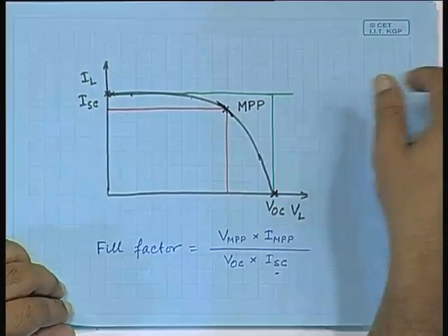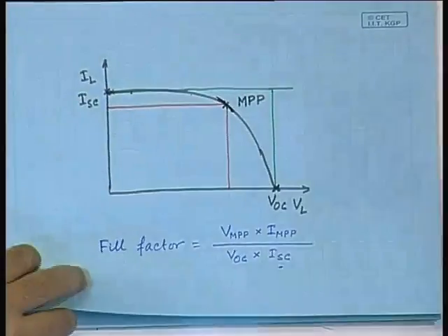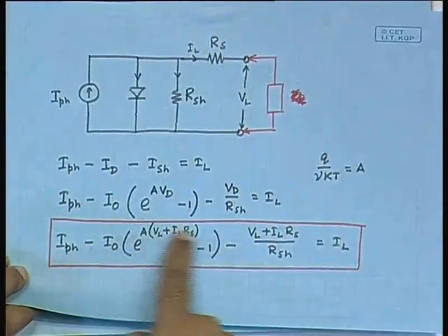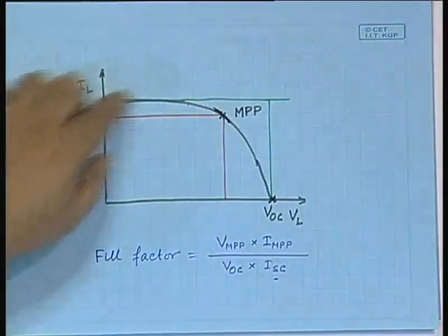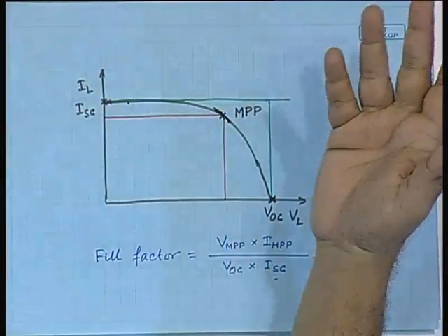But at present we can say that there are strategies, and one of the simple strategies in tracking any maximum: you might know the characteristics of the particular panel, means you might know the parameters that are used, as a result of which you are able to calculate where the MPP is for any insolation and you track it accordingly, but that will require a bit of computation power.